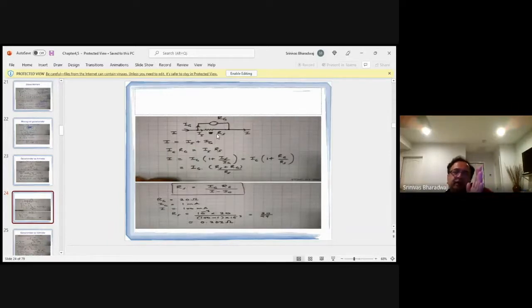Okay, so based on the size of the incoming current and the maximum that it can bear, you have to adjust the shunt resistance. I don't know if you've seen these ammeters, they will have another switch which will then change the shunt. So they will put another shunt, and that will cause the small galvanometer to support a bigger current. Okay, therefore I equals Ig times (Rs plus Rg) by Rs, right? You know how that works, right?